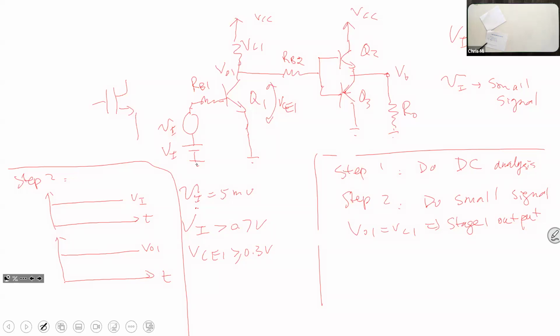But for all electronic circuits, we don't usually change the DC biasing. Once the DC biasing is given, we fix it. Well, what we change is little Vi. So if you add a little Vi, let's say it's a sinusoidal signal here, right? So imagine that you add this little Vi on top of that capital Vi. What's going to happen at VO1? So initially, without little Vi, it's a DC voltage. Now you have a little Vi added. So imagine that it's going to have something. You're going to see something, right? So you might say, okay, what exactly?